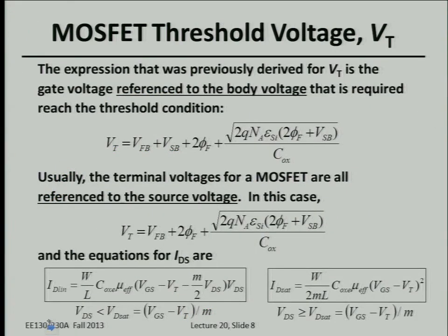Okay. So far, we keep introducing the variable called threshold voltage. I made this slide just to avoid confusion between the different definitions of threshold voltage. In a two-terminal device, like most capacitor structures, we take the substrate, the body, as the potential reference, so that's what every voltage is based on.